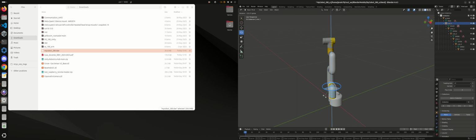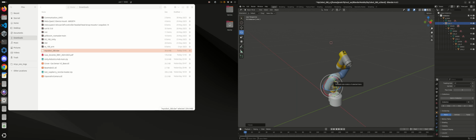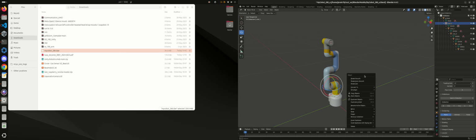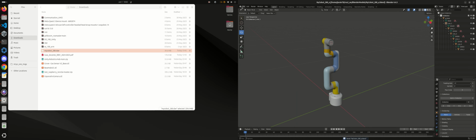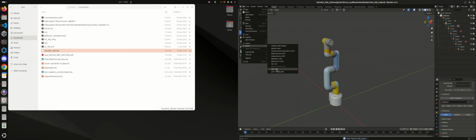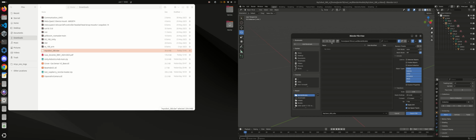that it moves, but the rotation is not a good rotation because it starts to rotate in this position. So we can move here, but okay, we can see that it rotates in the bad way. Okay, but all the joints are being linked. So next, Control S. The next is export to FBX, so we can export to our Unity project.